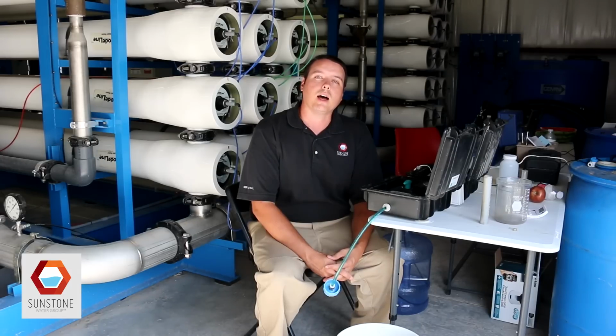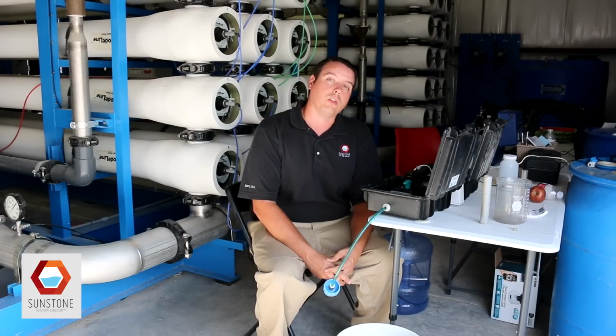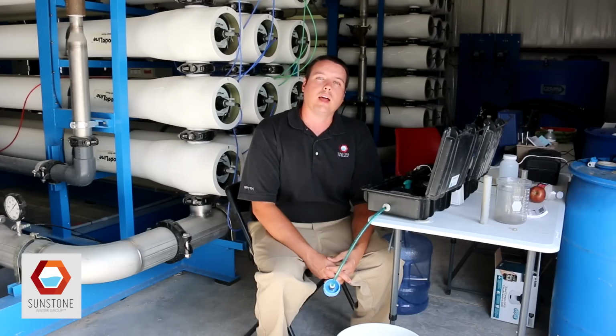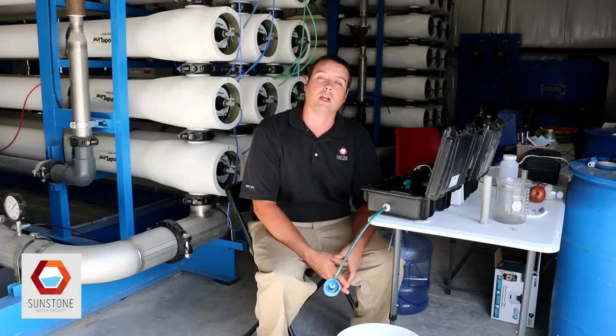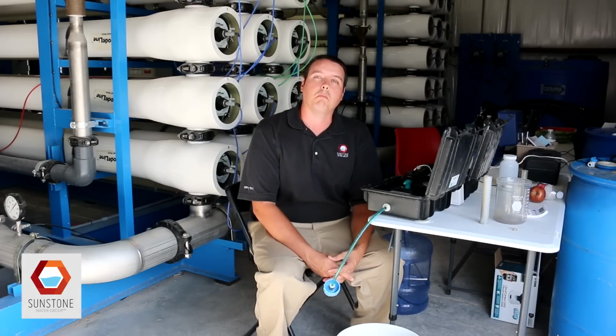If we end up with a high SDI number, as we saw in well water, adding steps of pretreatment can actually help reduce the potential for fouling in an RO system. So as you saw, we went from greater than 3 to less than 2. That's a significant decrease, which means an RO system like this will be able to run for a much longer period of time, purifying a lot more water in between downtime and cleaning.